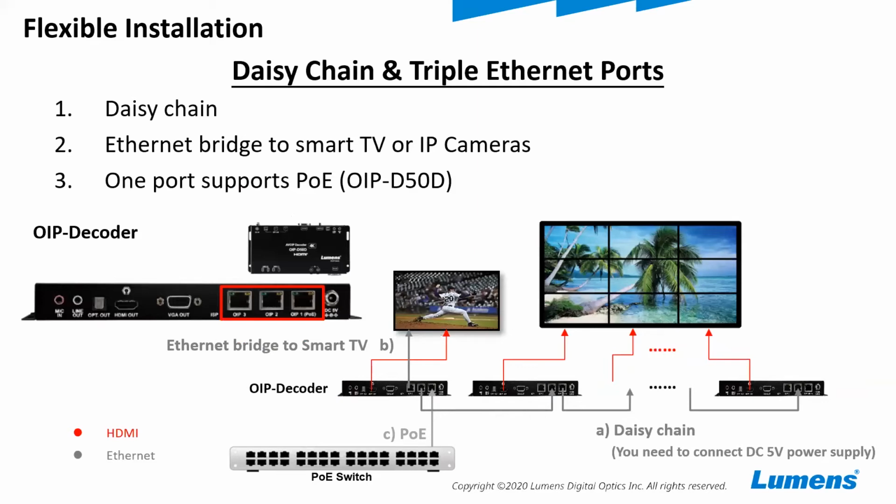Another aspect of the flexible installation is the ability to daisy chain our 50 series decoders. The first decoder in the line supports PoE, whereas the next set of decoders in the chain will need to be powered with a 5-volt power supply that is provided. Again, this is just another ease of use feature and ease of installation feature for our products.